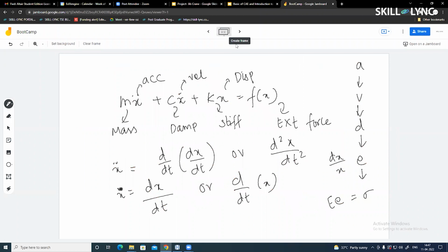Similarly, my dynamic analyses are all products of time, or let's say they are all dependent on time. For instance, in the event of a car crash, I'll basically give my boundary condition as velocity. So what is velocity? Velocity is displacement over time, where I have a fundamental parameter which is dependent on time. All these conditions and boundary conditions which are dependent on time are usually considered dynamic analysis.